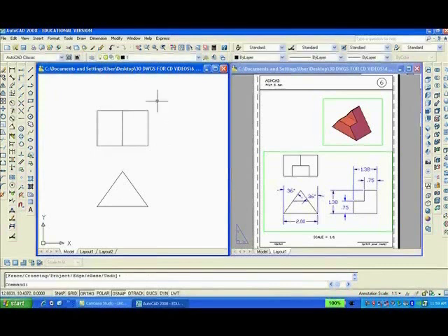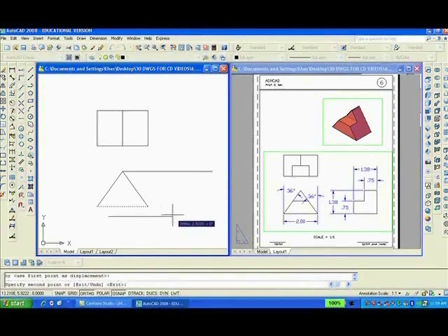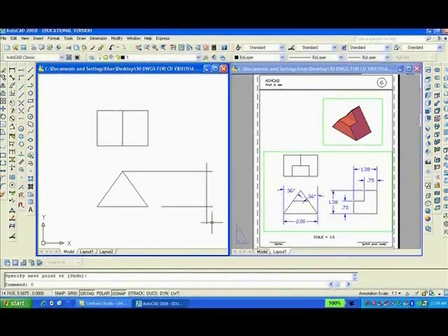Now I can offset. Well, I might as well draw the right side view. I'll draw a line from here like that. Then I'll simply copy this line. And I'll draw another line. You can call it construction line. And I'll offset, enter, 0.75, enter, in this direction, enter twice to repeat the command,